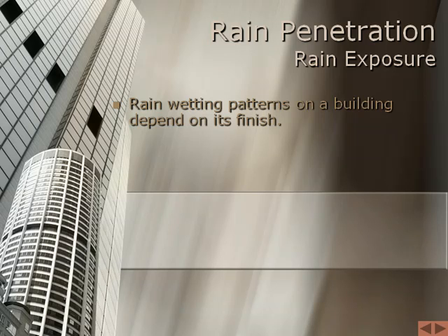Wind flow around corners and parapets can also draw water laterally and even upwards. This lateral flow can bring water to vertical joints, which are often quite vulnerable to leakage. Understanding wetting and wind patterns therefore suggests some design solutions and precautions regarding rain penetration.